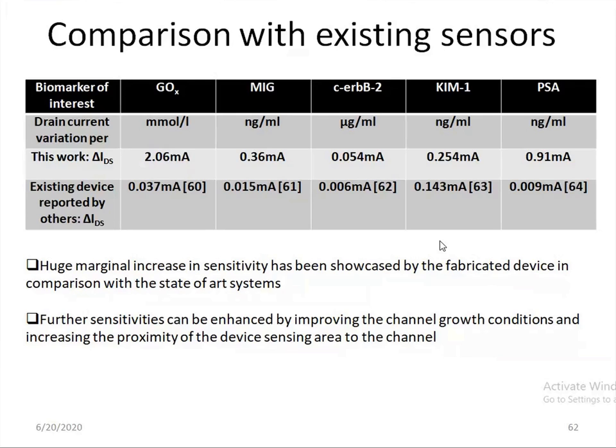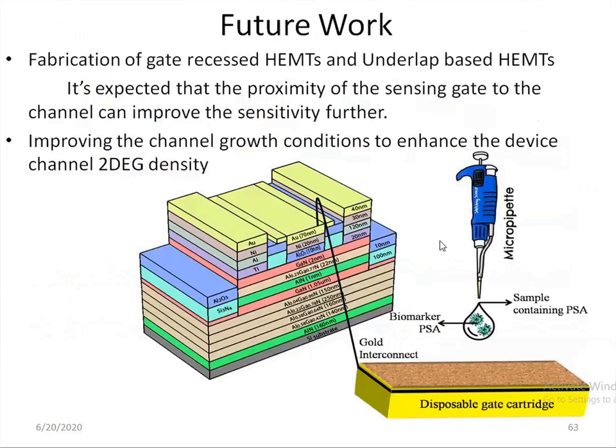There is a requirement of a large number of sensors today, and GaN HEMT is one such device that stands as a promise in the sensor domain, because its response time is very low. High frequency operation guarantees lower response times. If we can go for modeling or developing a HEMT device that can be used as a sensor, then it will be a very big achievement, and we can use even high power, high frequency domain devices for sensing applications, provided that fabrication is feasible in India. This is the future work that we are planning.